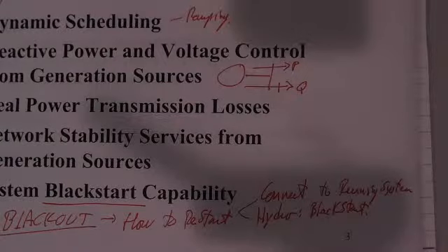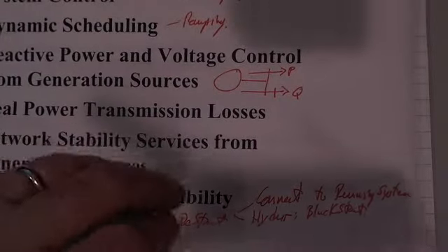The truth is, so do wind generators, so do solar photovoltaic systems. They don't need to have power coming in in order to begin to produce power. But most large power plants need to be connected up and to receive power in order to get things up and running again and start generating. That's why if you have a blackout, it takes many hours, let's say 12, 18, 24 hours of work to restart the whole system. It's not an easy thing to do.